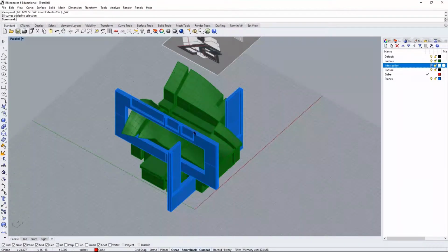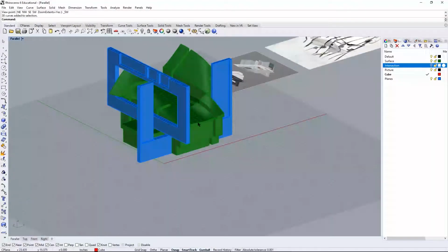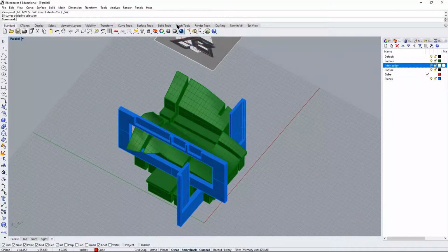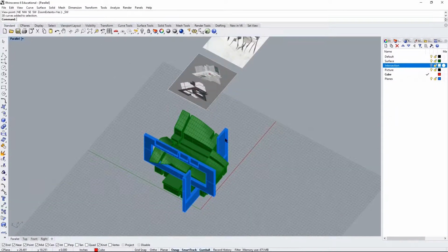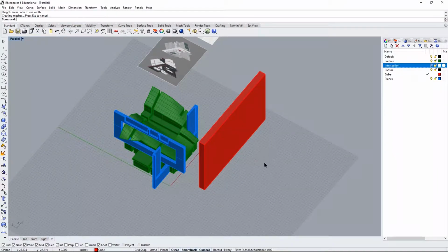All right, so that's starting to look pretty decent. You can see that I subtracted some larger areas away and did a little overhang, some small channels all the way through these planes, to emulate it. To do all those operations, again, I'm going to reiterate that your Boolean difference option is the way to go. And just remember your Boolean difference and split command will be the best approach to generate these forms.